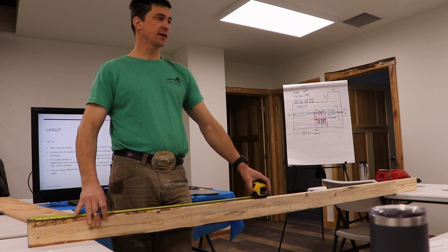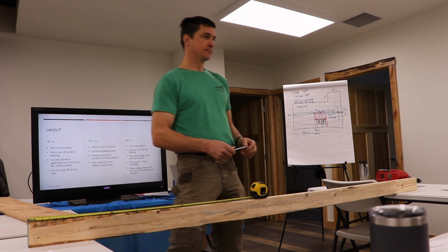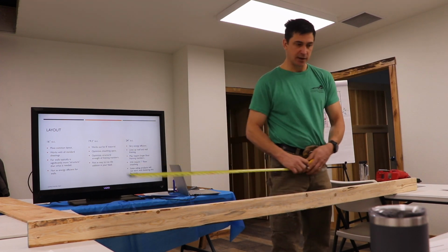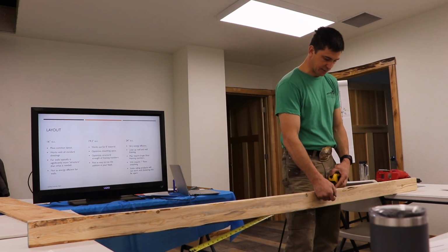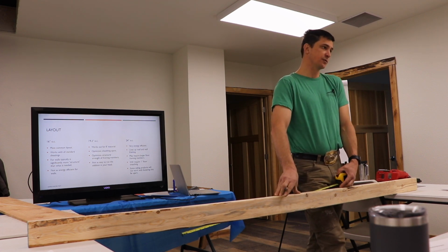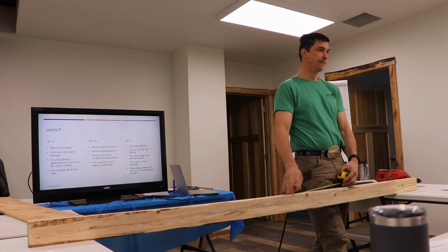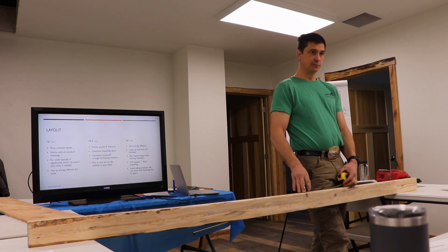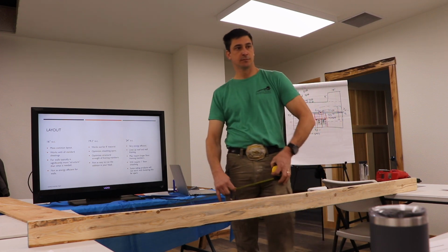Okay, how much back did I cut that? I don't know. Okay, so I marked it at 191 1/4, and then I cut it off at 192. Because we're framing the wall, so our studs are 1.5 inches wide, right? So it's 3/4 back. So you just go 16 on the center. Okay, so just 16, okay.